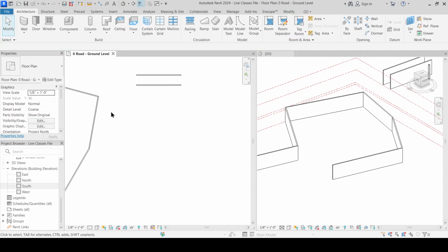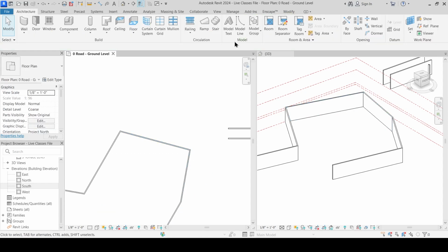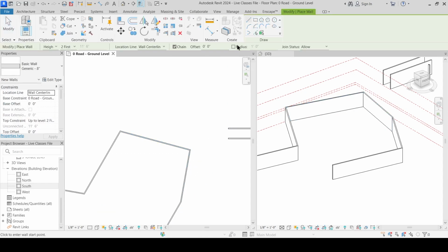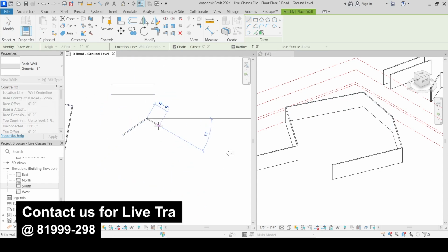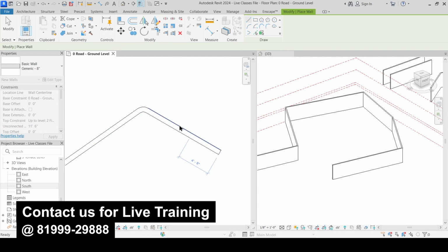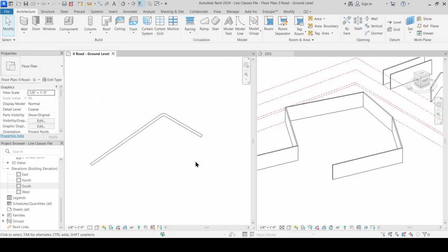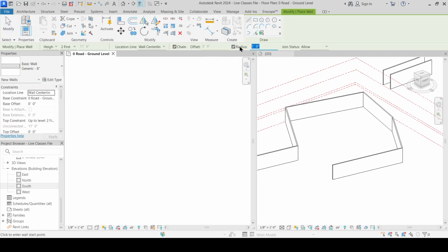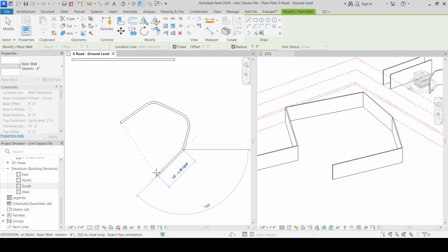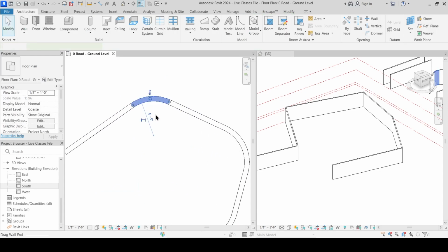Okay. Let's say that you have these two walls and WA, the radius. I want this radius to be 1 foot. So the fillet is very less. So just delete it, and WA, and with the radius I will enter 5 feet and then I will draw. So can you see the blunt edges? Okay, you can delete this and you can join this wall.